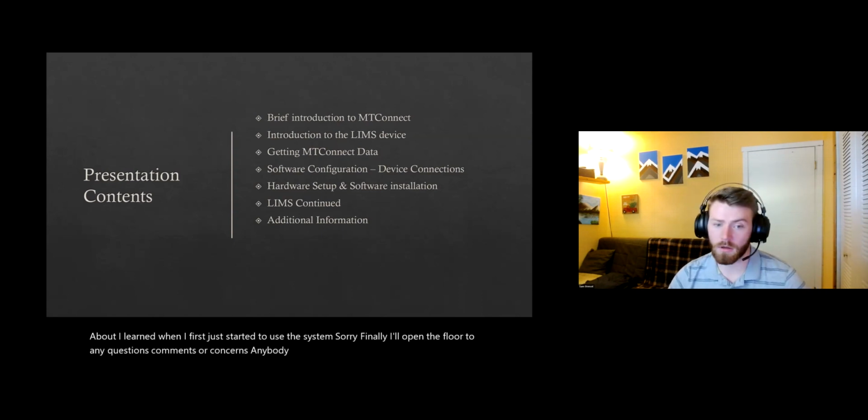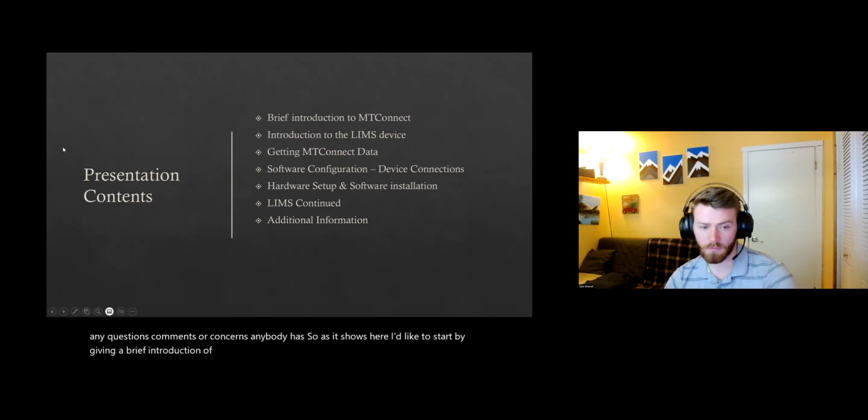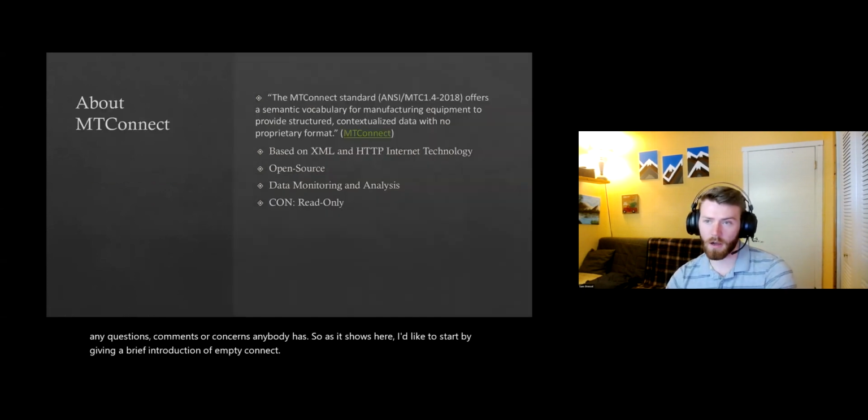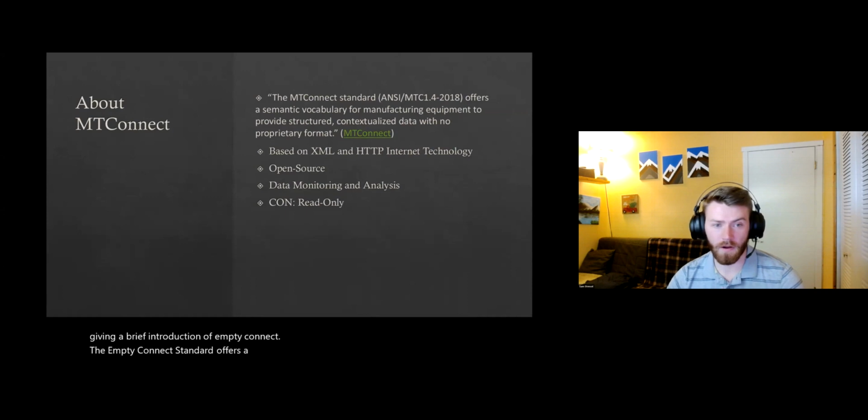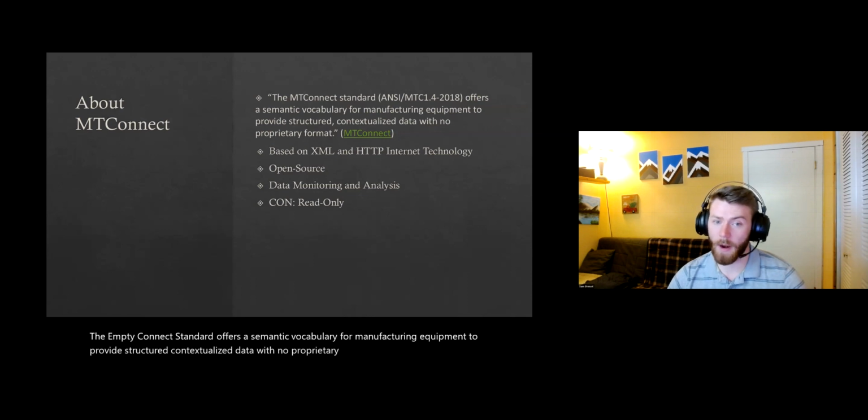So as it shows here, I'd like to start by giving a brief introduction of MTConnect. The MTConnect standard offers a semantic vocabulary for manufacturing equipment to provide structured, contextualized data with no proprietary format. MTConnect uses a programmable adapter to read the data of devices and then presents the data in XML format, where an agent is programmed to retrieve specific information via HTTP from that address.